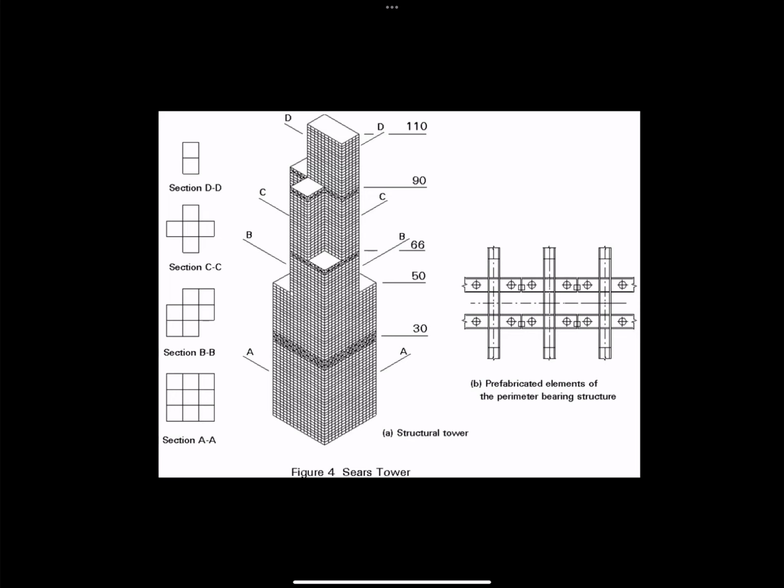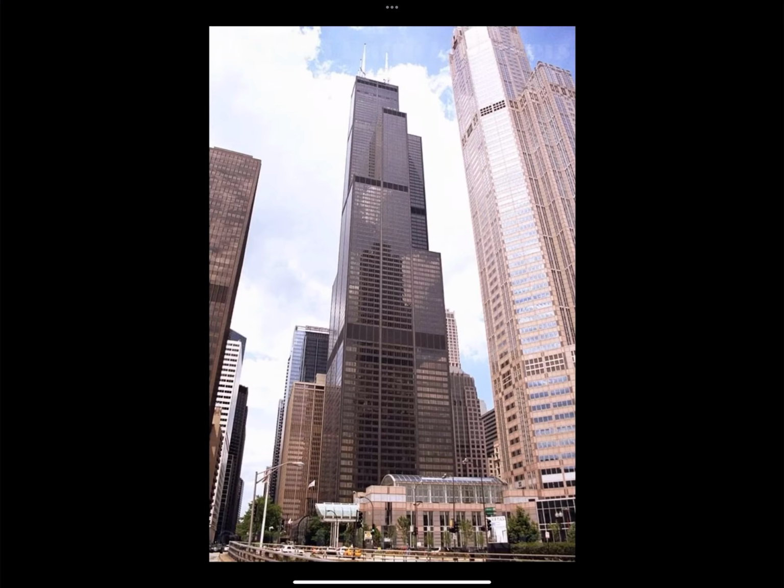And then those belts are 2-story high spaces with louvers, which you see in the right-hand image, and these are the mechanical plant rooms. And so each mechanical plant room serves down 15 stories and up 15 stories. So this belted structure is performing both structurally and in terms of the delivery of mechanical services. So here you can see the louvers on the facade for the belted structures.